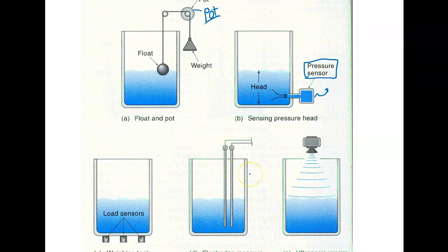So capacitance, by the way, is a real popular way to measure fuel in an airplane fuel tank. Just use a capacitive probe. The airplanes that I worked on in the Navy used capacitive probes. When the liquid gets up between the two probes, it changes what we call the dielectric constant, or the opposition between the two probes. Then they measured that, and that's how we actually got a fuel reading.